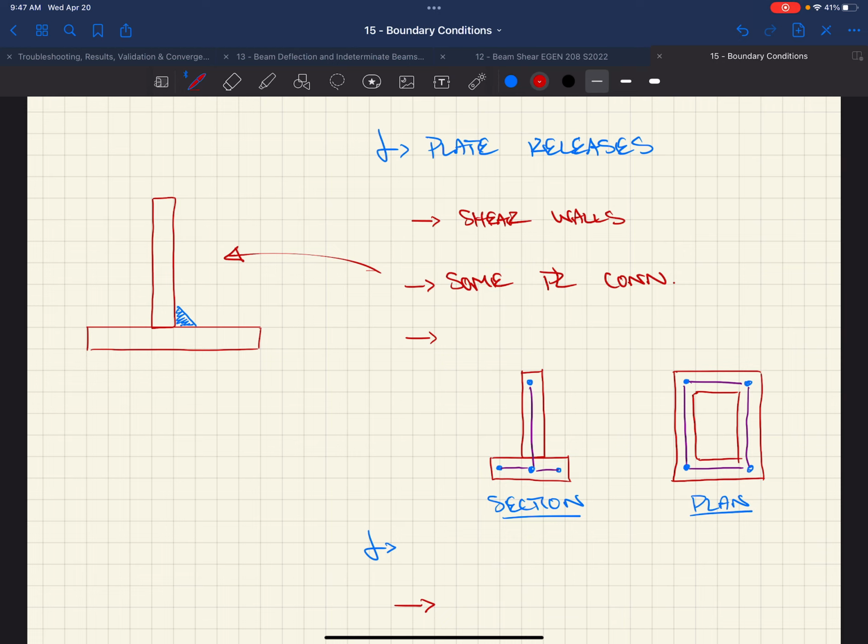Or if you were building a built-up member, or say you had some weird shear connection where you put 2 plates next to each other, and you decide to run a fillet weld along one side. Obviously, the resistance for this plate in bending is going to be very limited. So I wouldn't want to design this for bending, so I would release the moment capability of this plate at this connection to make sure that we don't have any moment, and the load that it would carry goes somewhere else. It's got to be carried somewhere. If we say that it's 0 moment there, we're going to design it to go somewhere else, right? Some wall intersections.